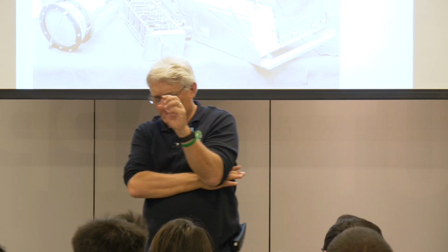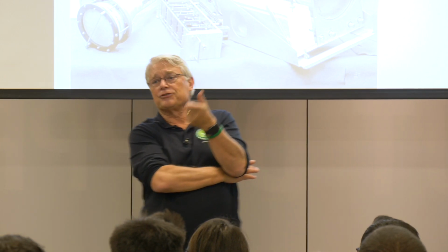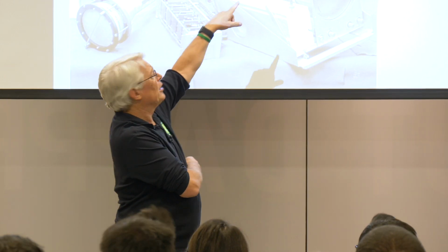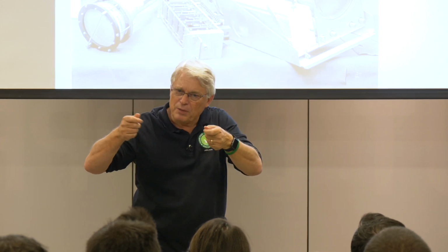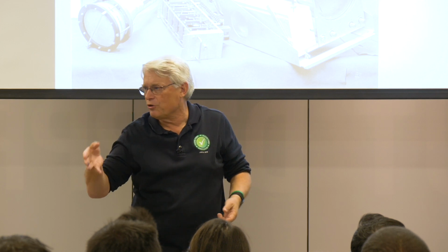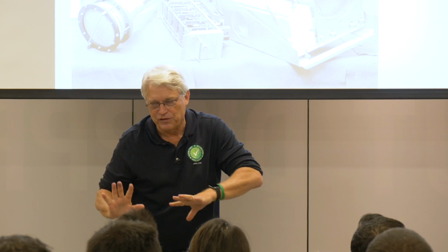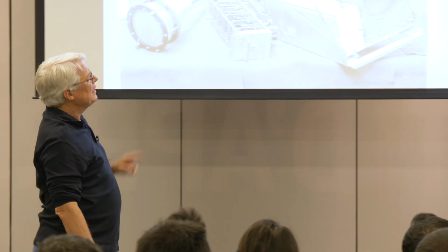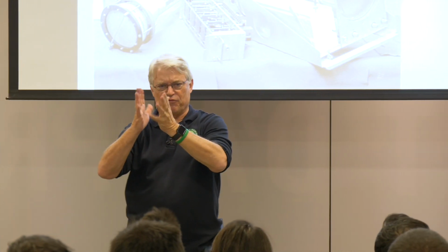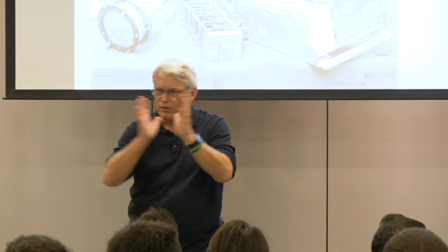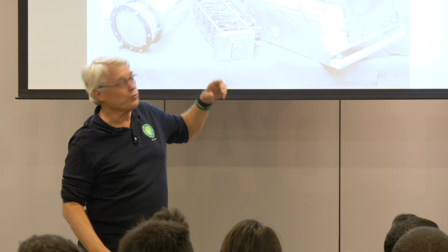Why did that happen? Well, it's because the cathode ray tube had a filament at the back end, and that filament would throw off electrons. And the electrons would move forward towards the front of the tube where there were phosphors, and the phosphors would glow. You turn off the tube, you turn off the TV, but the filament's still hot. It takes a long time to cool down. It's still throwing off electrons, and you still get that little spot, until finally the filament cools all the way down. The other thing about a cathode ray tube is that they used these plates. They put voltages or currents through these plates, and they could move the beam. So they could sweep the beam across the tube. That's why televisions work, by the way.